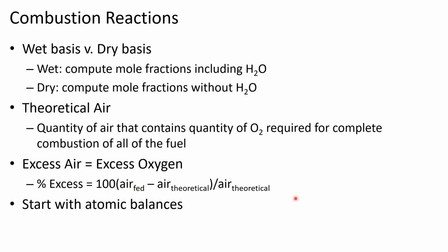I'm not going to go through the proof of that, but if you like, you could probably go through that very easily by simply realizing that air is 21% oxygen. So if we multiply top and bottom of this fraction right here by 0.21, we get the amount of oxygen that's fed and the amount of oxygen theoretical. And for these problems, as with most of the reactor problems we've worked, we're going to use atomic balances.